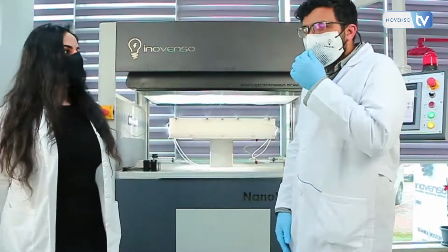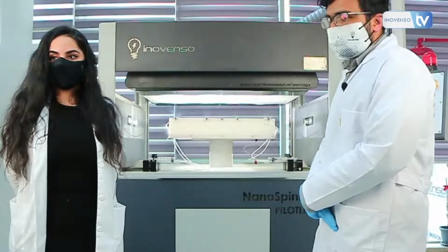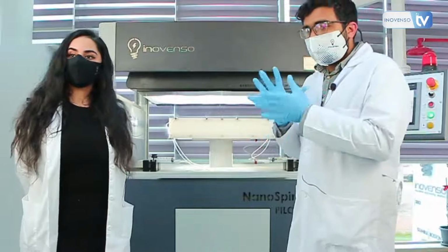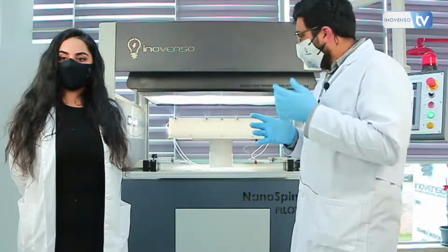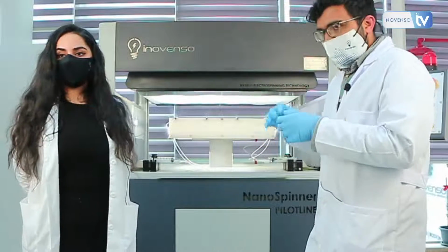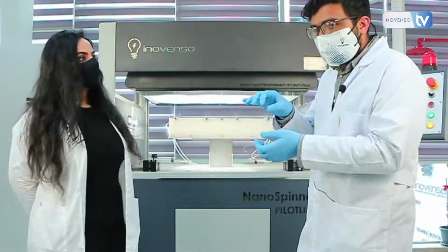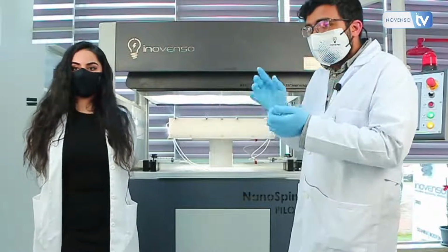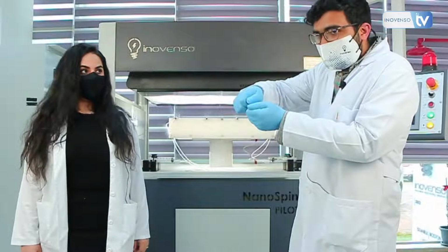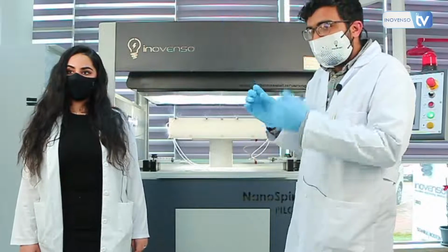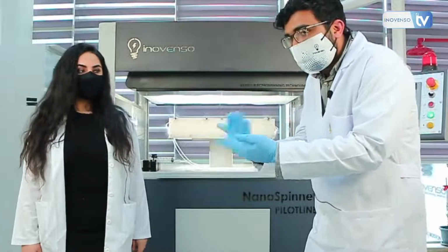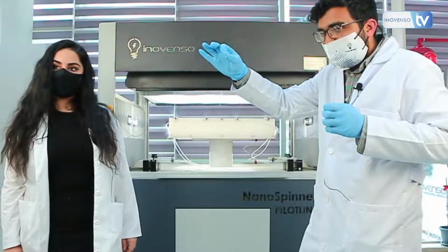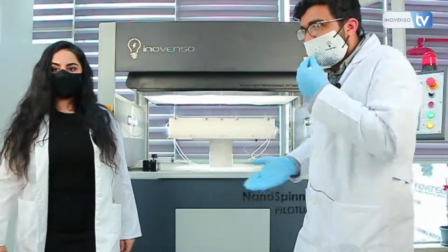So actually, electrospinning and electrospraying are sister processes. They're essentially the same thing. The main difference is the polymer entanglement density, or how thick the polymer is, or its concentration. Just to give you a small scientific background: as you put a polymer solution into a high electric field, it starts extruding in jet form. If the solution density isn't strong enough, these polymer threads will start rupturing into particles, snapping into particles, and thus you will get electrospraying. If they're thick enough to not be ruptured, you'll get these extremely thin nanofiber lines, and that process is called electrospinning. It's essentially the same.